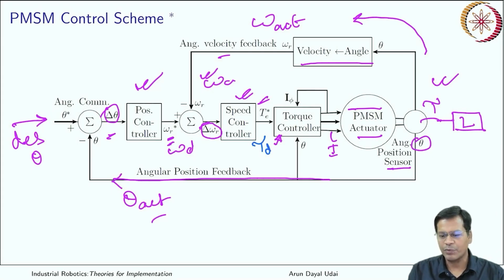So that model, by measuring the current in its coil, is able to estimate the actual torque. So this is the desired torque, this is the actual torque. The difference is used by this torque controller. Ultimately it gives you an output which is current.